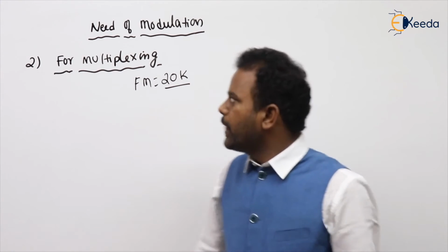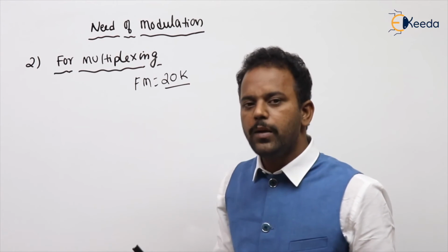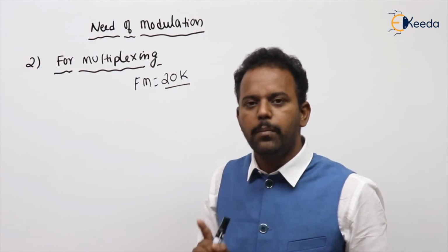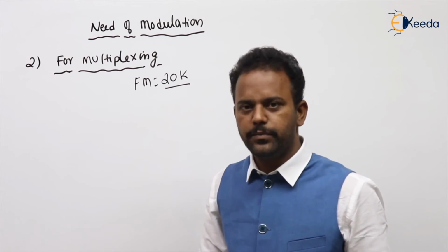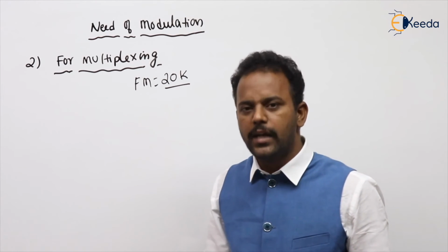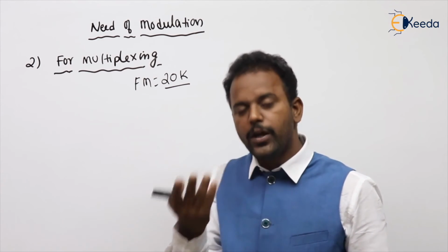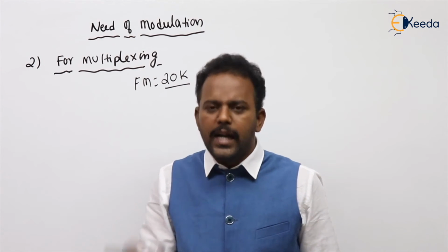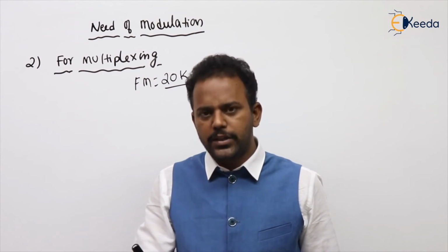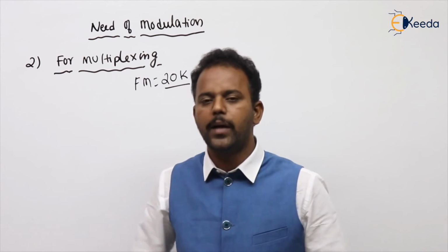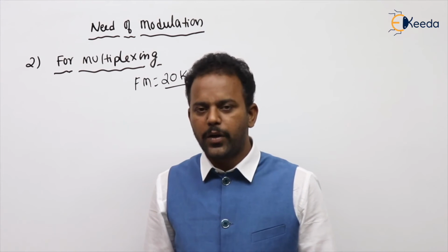So anyhow, this multiplexing will be possible only if you do the modulation. Without modulation, multiplexing is not possible. Do you understand my point? For example, if you want to multiplex voice signals, the modulation scheme we use is SSBSC. Why SSBSC? SSBSC has better advantages in terms of bandwidth and in terms of power. We will get back to that point. Did you get my point or not?